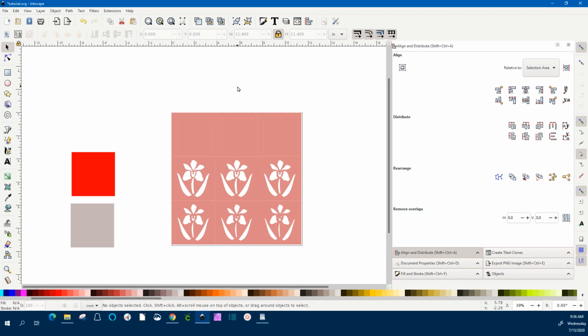And when I cut these in Design Space, I'd like a little space between each of these squares. So I'm going to put about 2/100 of an inch between. To do that, I'm going to move the center row down 0.02 inches, the bottom row down 0.04 inches, and then do the same thing with the columns.